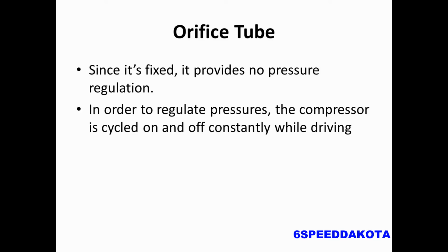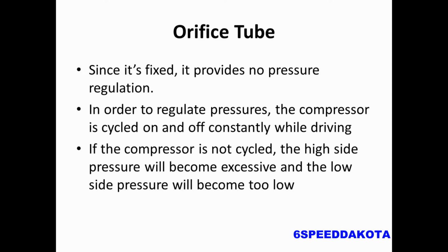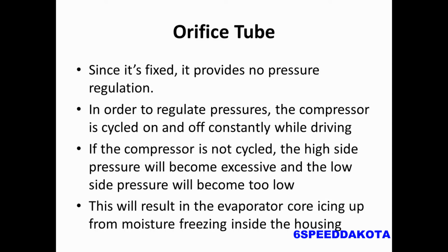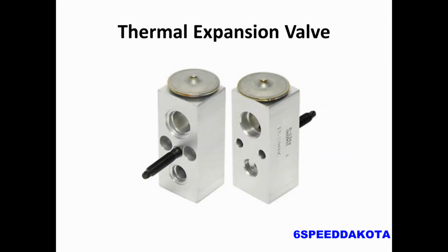In order to regulate the pressures, the compressor is actually cycled on and off while you drive. Sometimes you can hear the compressor click in, and it'll kick on for maybe 5 to 10 seconds, then it'll kick off. If the compressor isn't cycled, the high side pressure can become excessive and the low side pressure will fall too low. And this will actually result in the evaporator core icing up from the moisture freezing inside the housing.